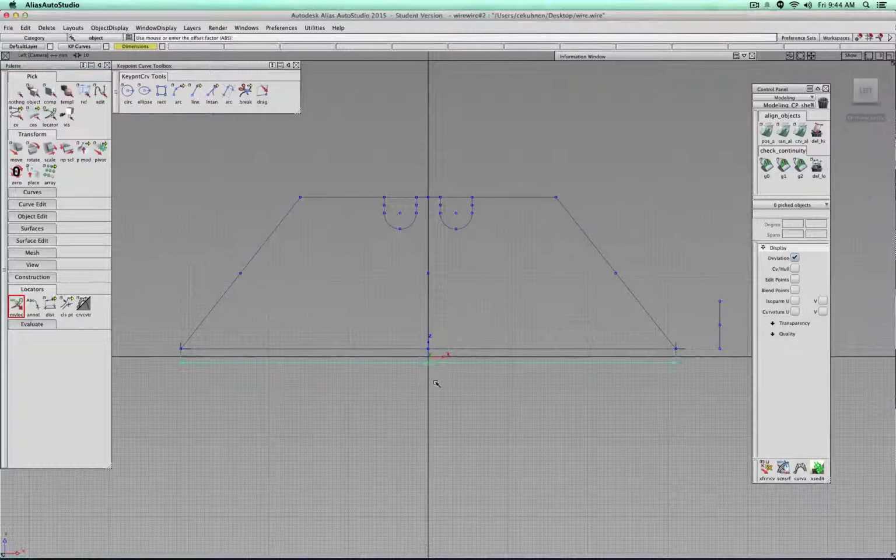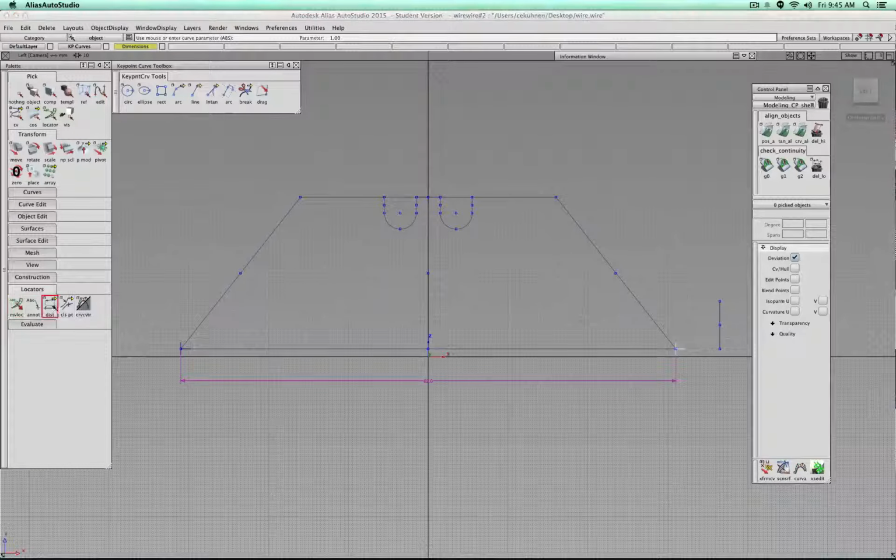So this one, for example, we can maybe move out a little bit. You can also, for example, measure half a distance on this line if you want to. So 31. Okay. Let's put on another locator there. So what's the point of locators? First, for you, you can always put down information about dimensions. Now this is of course a very simple object, but imagine you have a more complex design, multiple parts. You don't want to always have to measure something. So you create yourself the time to simply draw the stuff onto it.